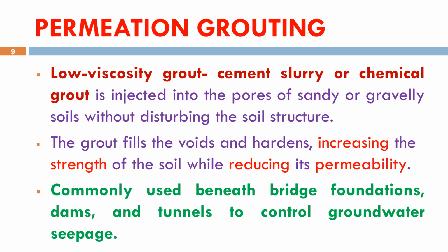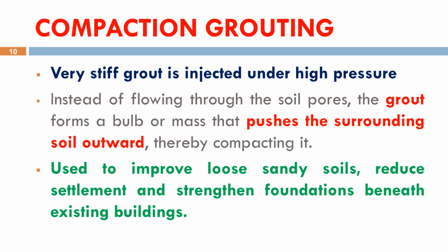Permeation grouting is widely used beneath bridge foundations, dam foundations, and tunnel projects where groundwater seepage needs to be controlled without causing any disturbance to the existing ground. The next method is compaction grouting.